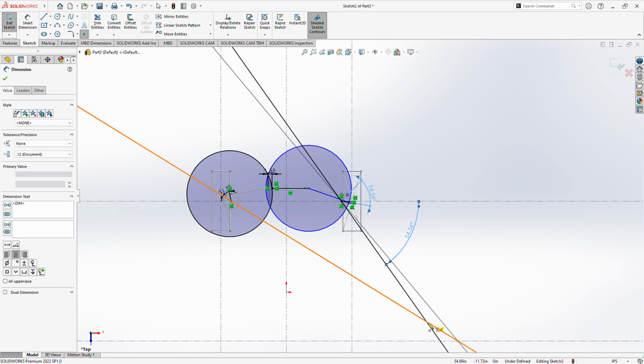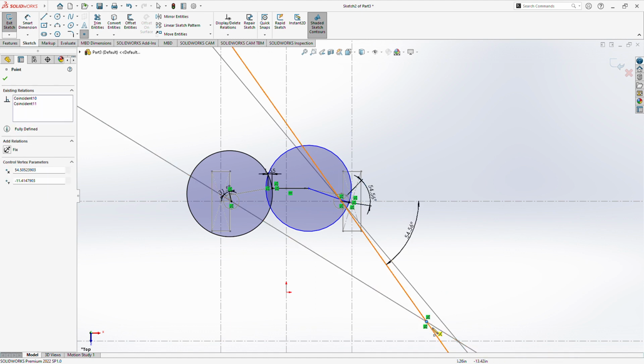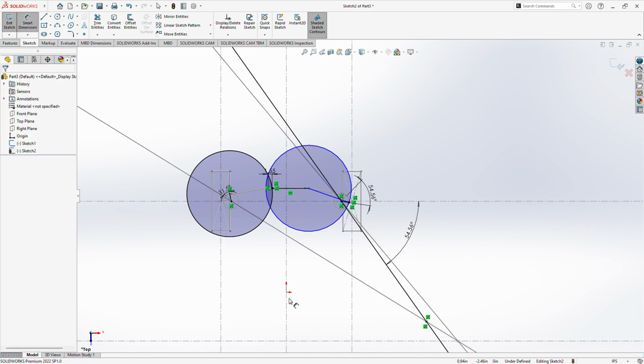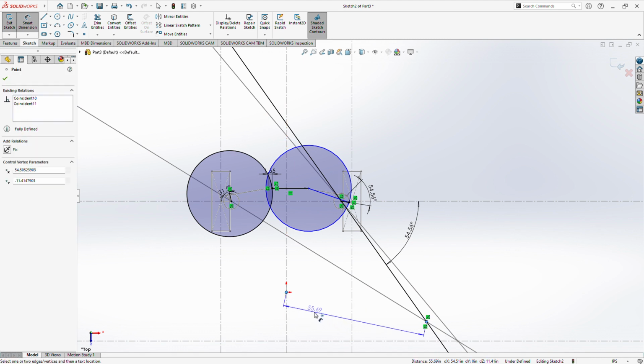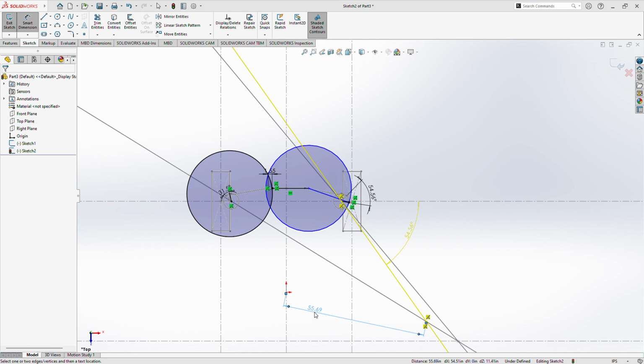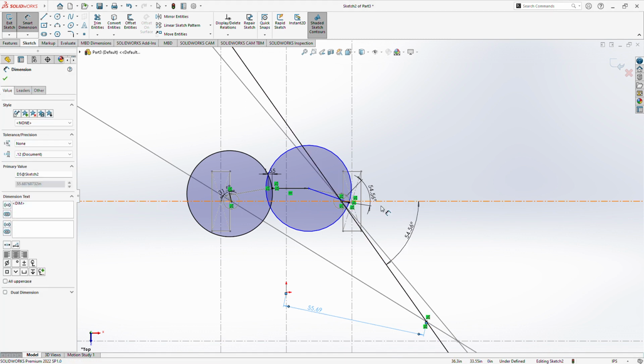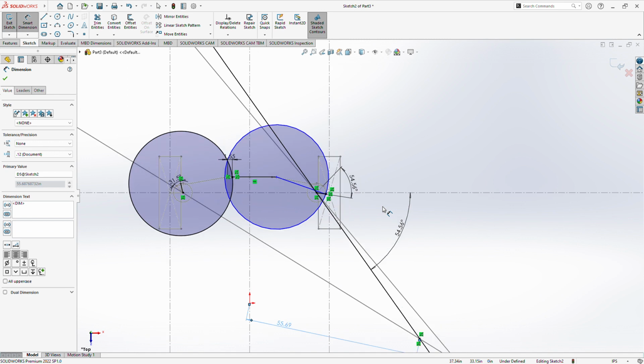Take a point. This is the actual point where the vehicle would rotate about to take a turn, and measuring this value and this value, the distance between them would give the actual turning radius of the vehicle. Okay, hereby the geometry is completed. Put the values in the calculations. The Ackermann percentage would come here about 97%. Okay, we have completed the geometry.